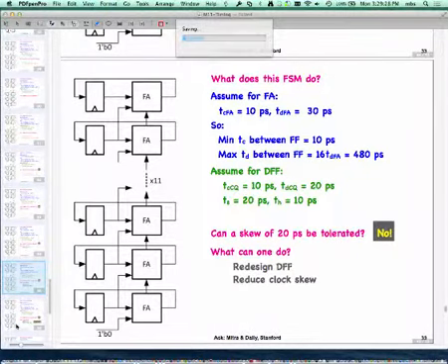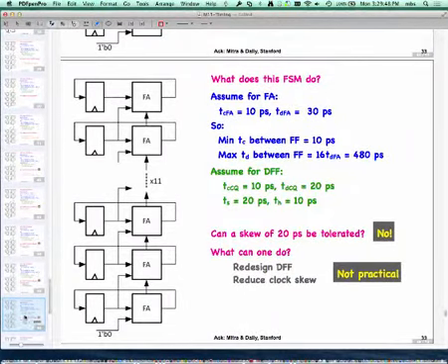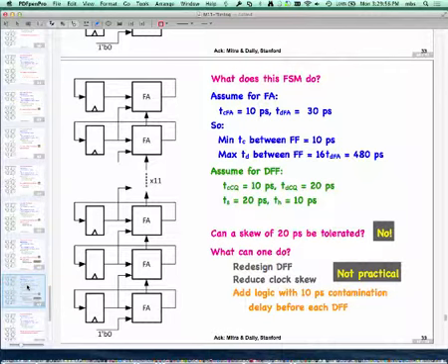And what that means is that you will rewire the clocks. So clocks are distributed all over the chip using a network of wires. So you are going to reduce the delays in those wires. The way to reduce delays in wires is to fatten the wires or whatever, just make the wires faster. So you're going to do that. So that's another option. And neither one of these things are really practical because basically in either case it means you have to go back to designing the chip.